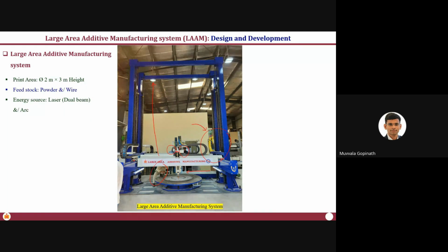Because, like I said, if you have a molten pool, the powder particles come and sit on the molten pool at the edge of its solidification. So if you look at any additive manufacturing surface, on the surface of the layer that is additively manufactured you will see partially assimilated or partially fused powder particles, which can sometimes get removed if you apply a little bit of pressure. Just imagine you make an implant out of that and it goes into the body.